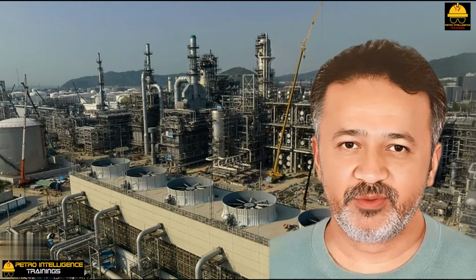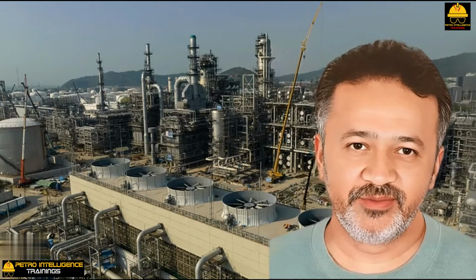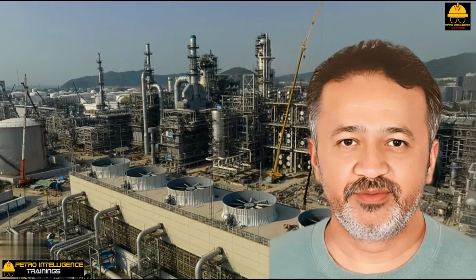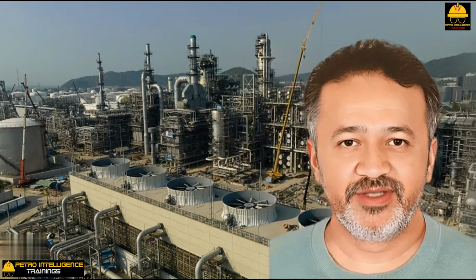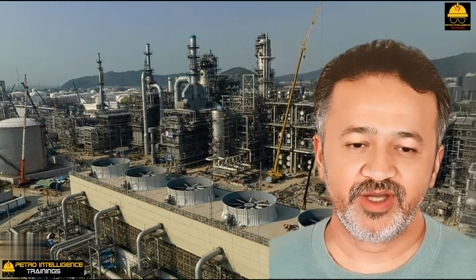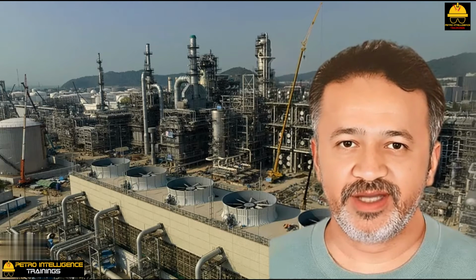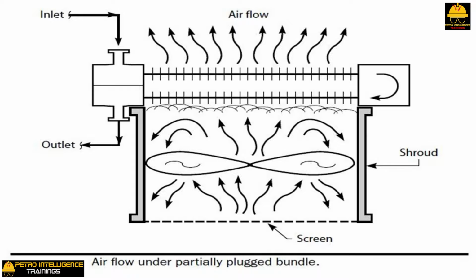However, note that for forced draft fans, the total airflow discharged by the fan remains constant regardless of the fin tube fouling. The fan discharge pressure remains constant regardless of the fin tube fouling. The amperage electric load on the motor driving the fan remains constant regardless of the fin tube fouling. Picture explains this apparent contradiction.